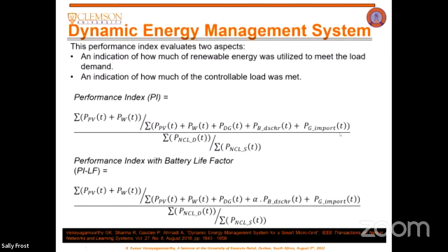How many times it's changing the status of the battery from charge to discharge, and how frequently. We do not want to frequently go charge, discharge like that. So we want to find the best way, how many minutes it should be on charge and then discharge depending on what the SOC is, and factor that into the index as well. And if we are able to get 1 after factoring that, then that's the best considering the life of the battery. So here's an interesting result we have.